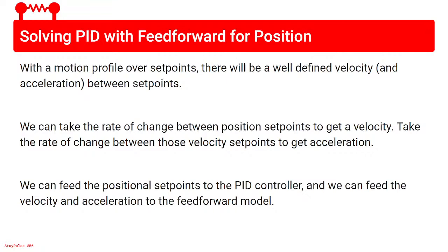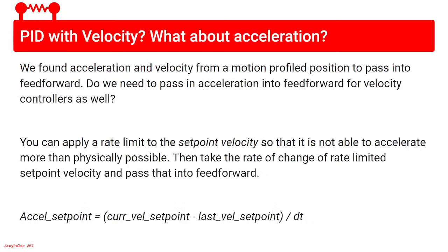But if feed forward is doing a lot of the heavy lifting, the PID constants can be smaller, so they can be less significant because they don't have to account for as much movement. So if you tune it with SysID, that's what you'll notice. So yeah, what's left? Oh yeah, one note.